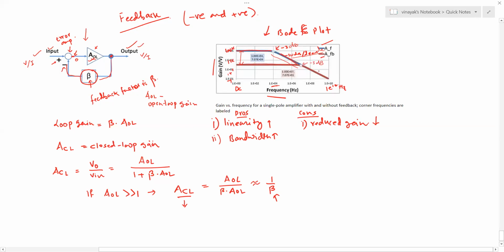Okay, and then again the slope is -20 dB per decade. Here is the slope. So from this point right here to this point, I have the frequency response change, and the frequency at which I have the first pole in the circuit is beyond 1 mega.